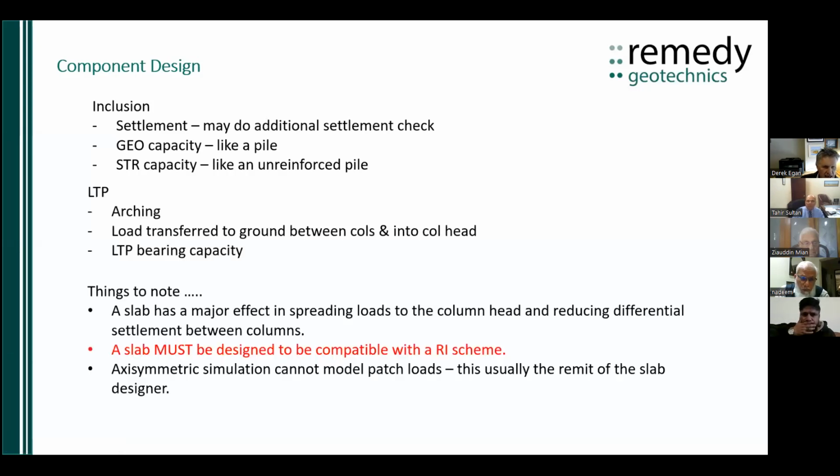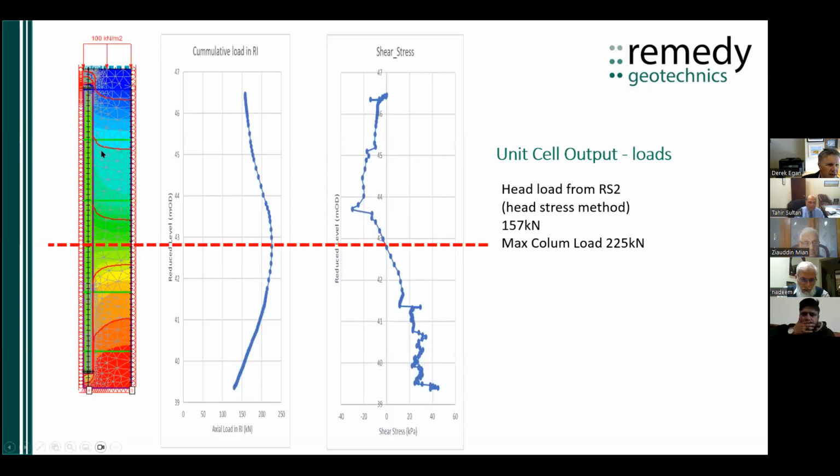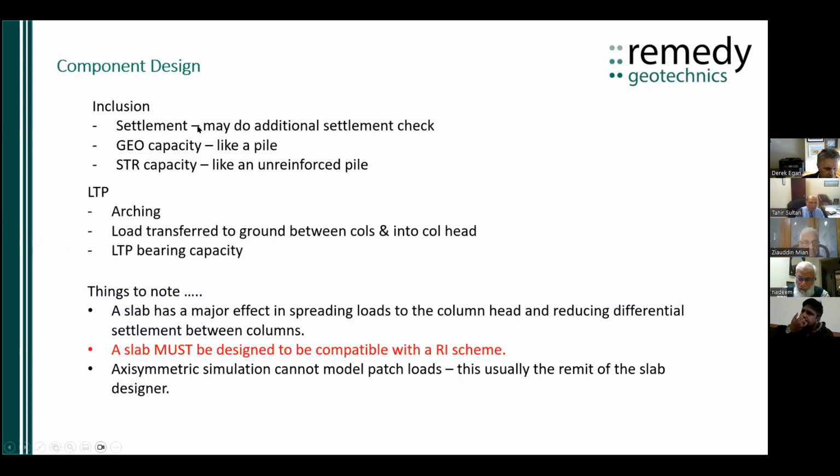Now, when we look at the LTP, we have to consider the arching and the load transfer in the ground between the columns, because we're getting load transfer into the ground there. We need to look at the LTP bearing capacity, which I'll come to in a minute.